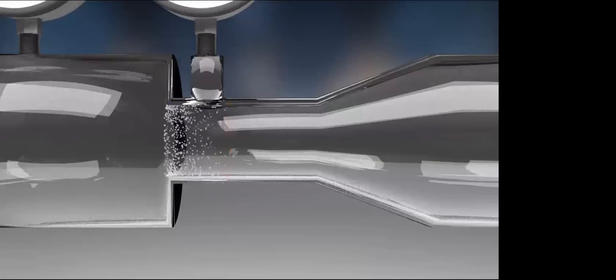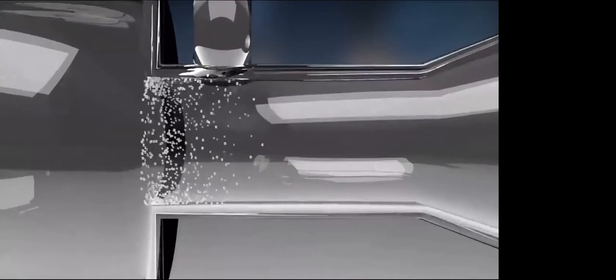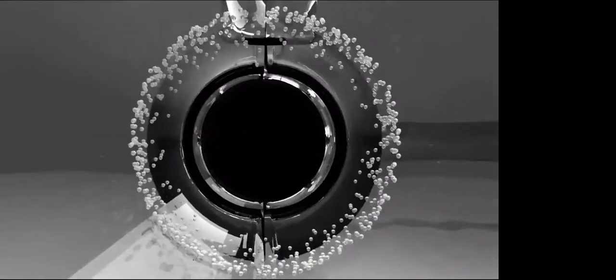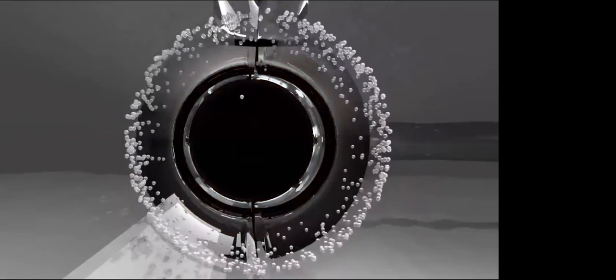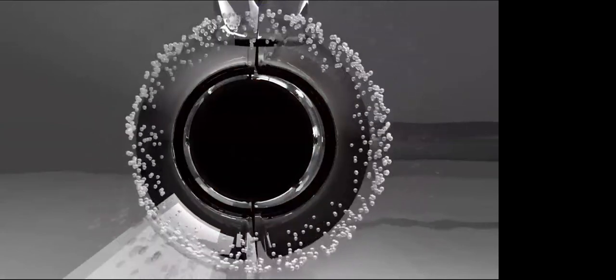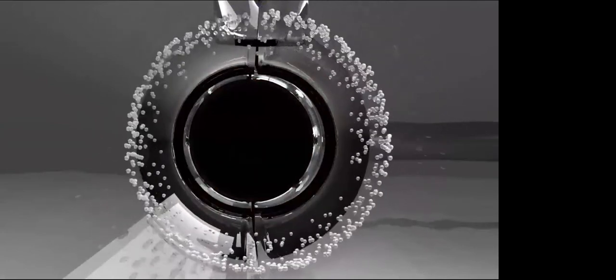Because water from the vapor bubble occupies 50,000 times less volume after having condensed to its liquid state, the collapse of each bubble is a spectacular event and emits pressure shocks. Pressure shocks from many collapses result in an audible noise very characteristic to cavitation. The sound used now in the video has been recorded in an experimental setup similar to the one in the animation.